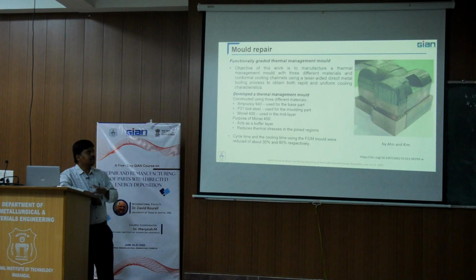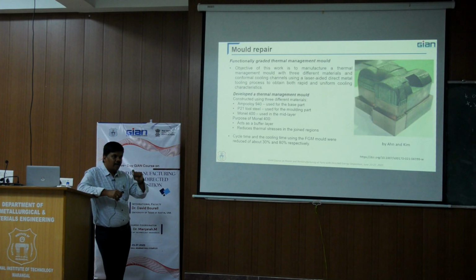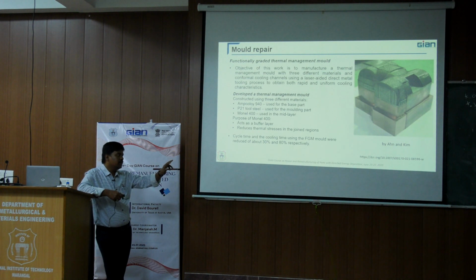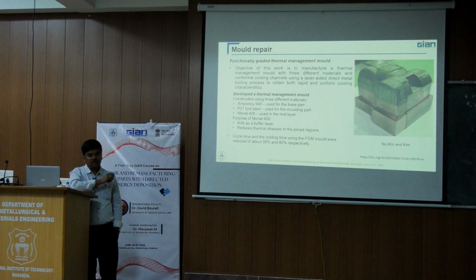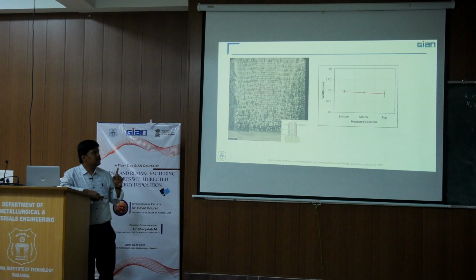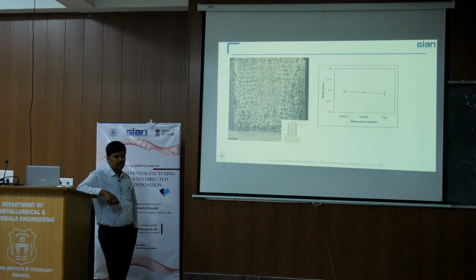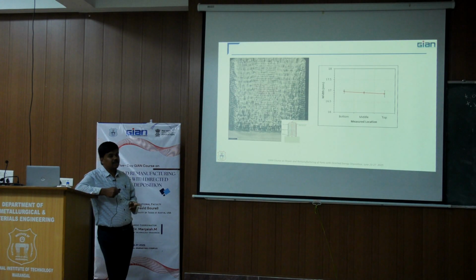And with respect to all these things, as I told, whether the repaired part will have the same kind of mechanical properties or not, how do we have to qualify? Yes, we have done the repairing. Does it have the same mechanical properties as the substrate? We have done initial preliminary studies with respect to some of the titanium alloys. We have taken the data of the surface deposition strategies, what kind of surface finish we are having, and what kind of microstructure we are getting.